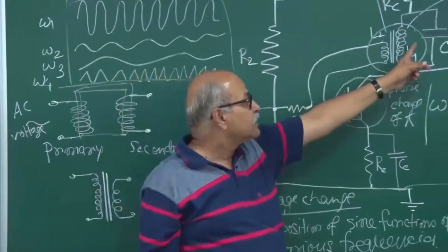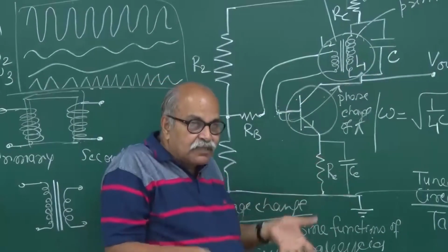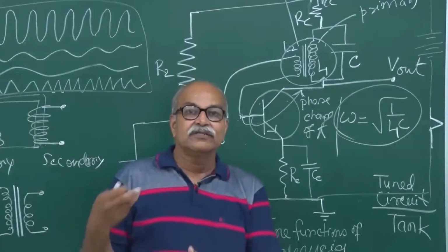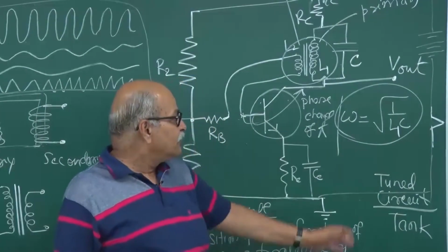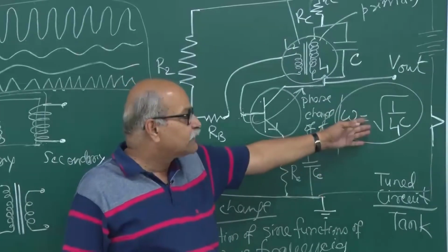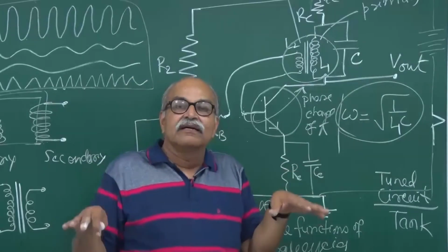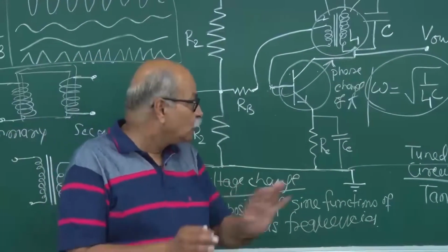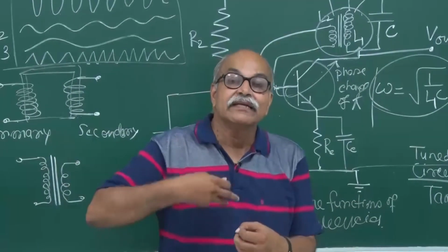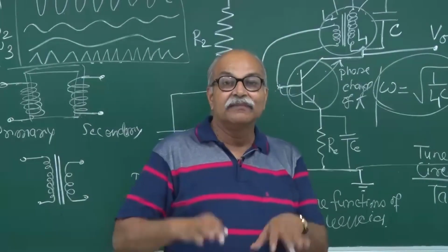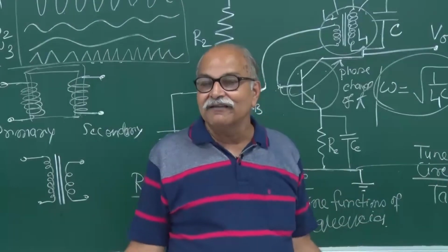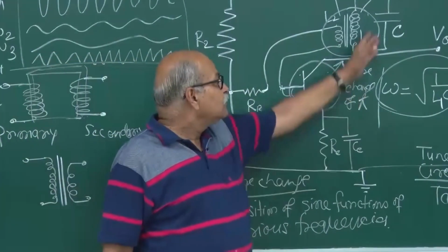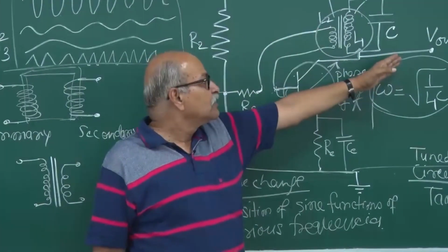But this is a circuit where, if the input going into it is at this frequency, then it oscillates with larger amplitudes. And if other frequencies come which are very different from this, those oscillations are of very small amplitudes. So out of the many frequencies which are there, it selects its own frequency, and that component will get enhanced again and again, and the remaining will die out. After a very short time, the other components all die out, and finally there is only one component, and then you have your cycle,